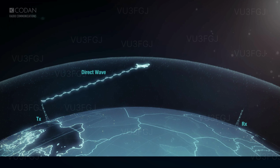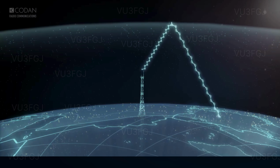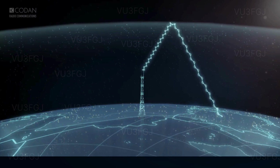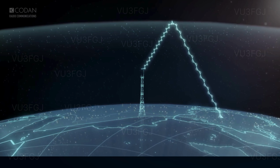Direct wave, which can be used for long-distance communication between ground stations and aircraft. And finally, skywave, which uses the ionosphere to refract the signal back to Earth at varying angles, providing long-distance communications. As you can see, skywave covers the maximum distance. We are most interested in skywave to propagate signals. A layer in the atmosphere called the ionosphere refracts the HF radio waves, making this technology work over long distance.